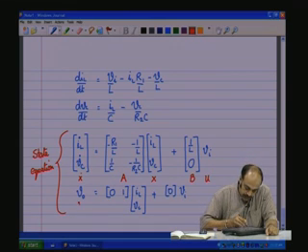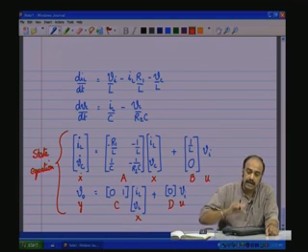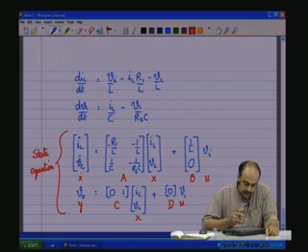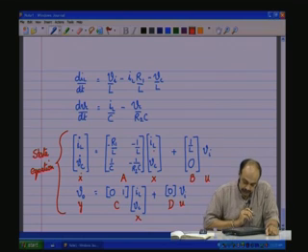And here you see this is the output Y, the C matrix here, because in this case V naught is same as V c, is the C matrix. This of course again is the X matrix. The D matrix is 0 because V I is not directly passed on to the output, and this is U. And you see that there is a one-to-one correspondence between the general standard representation of the state equation and this here. So, this is a complete mathematical representation of that particular circuit. So, all circuits can be represented in this form.